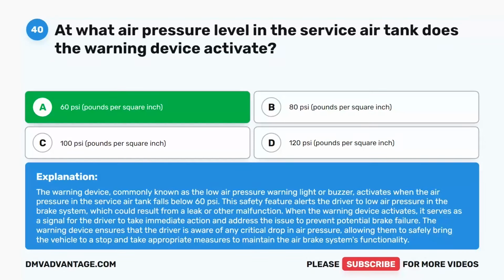The warning device, commonly known as the low air pressure warning light or buzzer, activates when the air pressure in the service air tank falls below 60 pounds per square inch. This safety feature alerts the driver to low air pressure in the brake system, which could result from a leak or other malfunction. When the warning device activates, it serves as a signal for the driver to take immediate action and address the issue to prevent potential brake failure.